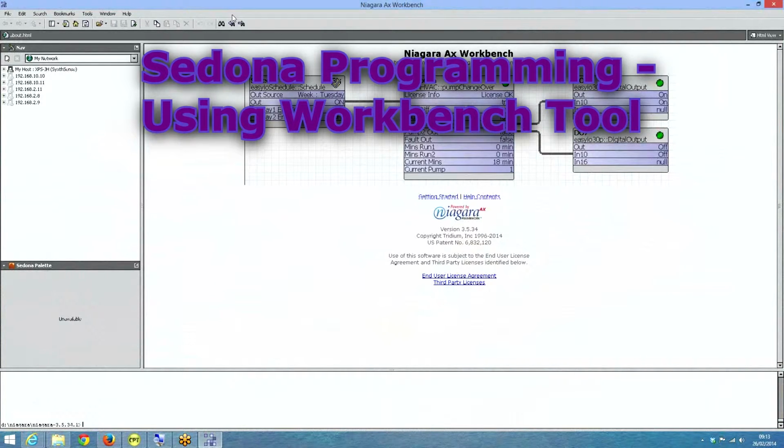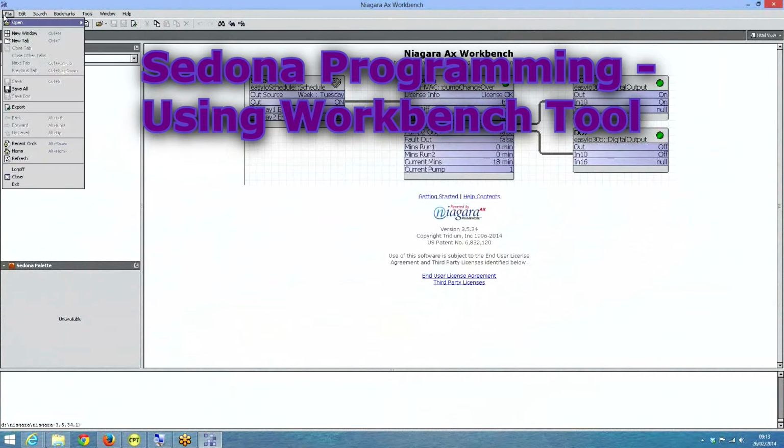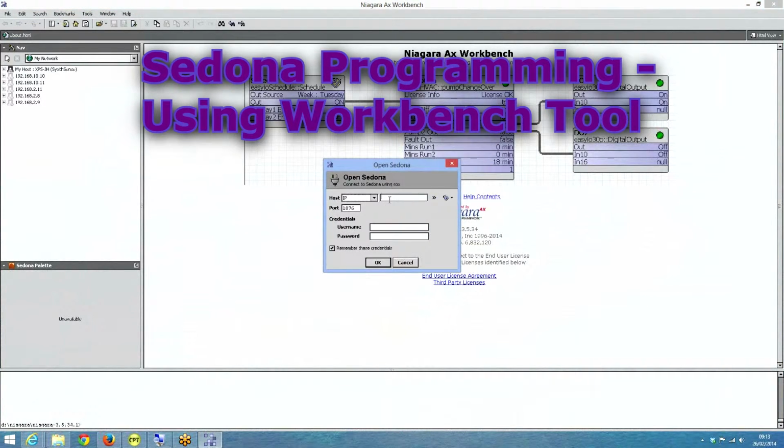In the previous videos, you saw how we program the controllers using the CPT tool. When we use the Workbench, it works pretty much in a similar way. Once we launch the Niagara Workbench, on the right-hand side, we have a navigation tree similar to the CPT tool where we have our controller addresses. If I double-click the controller address there, or I can go to File, Open Sedona, that pops up the screen for Sedona. I type in the IP address 192.168.10.11 of that controller, username admin, no password.